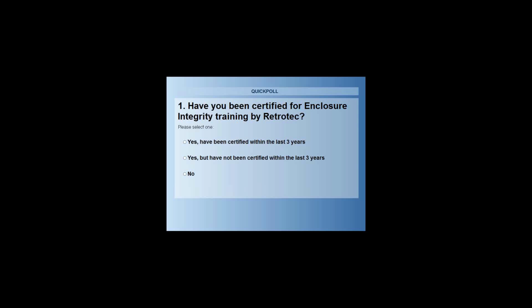The new reason for doing it is that the door fan test can also evaluate the enclosure for peak pressure that would occur during a discharge. Even if you are discharging, and I know in a number of instances when a discharge test has been performed for hold time evaluation, they've unwittingly overpressurized the enclosure and caused damage. So if you do nothing else, you should be using the door fan test to check for that.